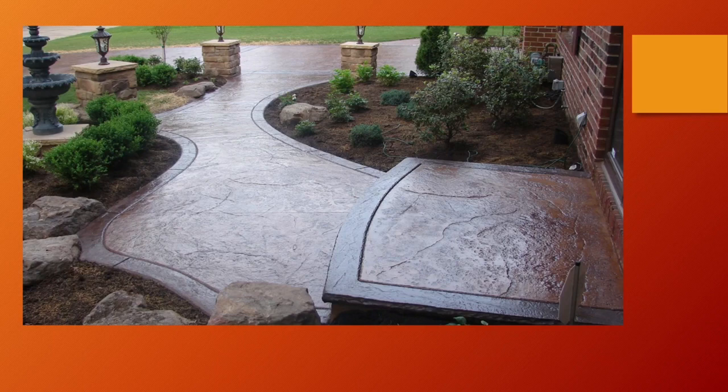This is called stamping. So we create molds, timber molds or metal molds around the step, and then we pour the concrete in, and then we have these large pattern stencils that are literally stamped into the concrete, which gives you all of the grain that you see inside of here. And then of course you're using different coloured concrete to give the contrast between the two. But again, a very durable looking driveway.